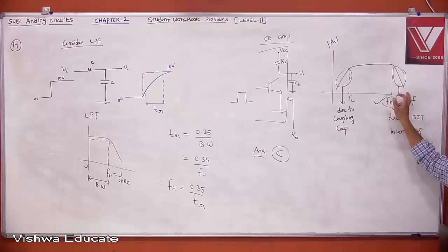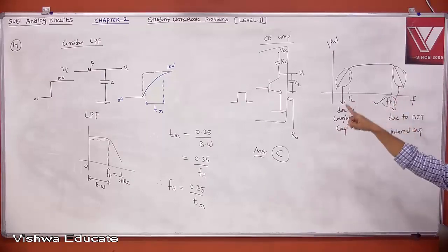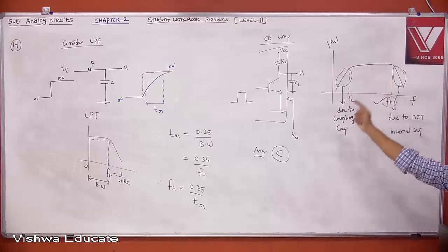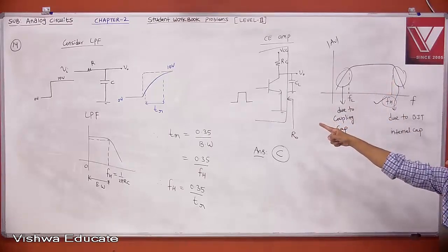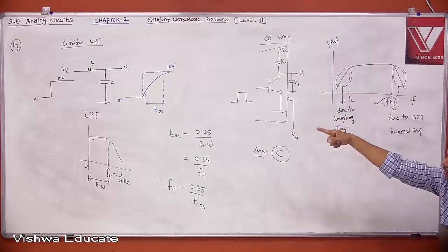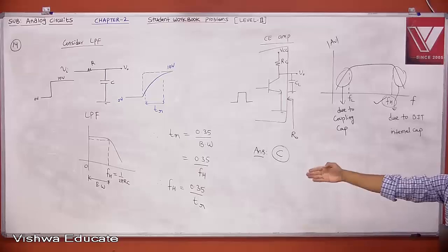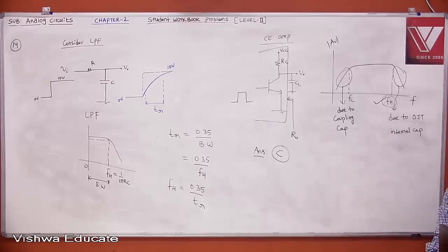For the high frequencies, which is nothing but a step, the transition, the rise time, your output is trying to track it, right? Then that is nothing but the rise time, which is compatible with your low pass filter. Then the higher cutoff frequency is the one that gives the relationship between rise time and the upper 3 dB frequency.